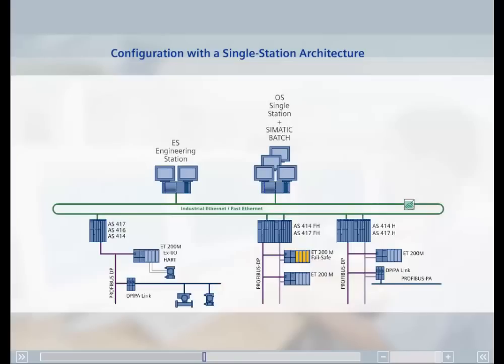and batch server and client functionality are installed. The PC should have at least 2 monitors, so that there is enough screen space to be able to control and monitor the Batch Control Center, Batch CC, and the OS at the same time.